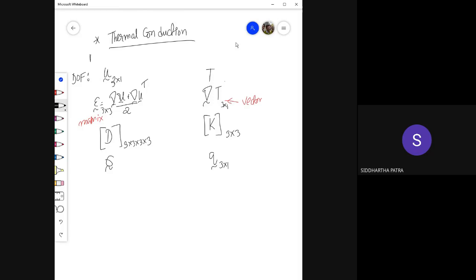There are two quantities. There is Q dot N, which basically gives you the heat flow rate per unit area, because this one is normal to a given surface. So that is how much is going past the surface. Let's say this is the heat flux Q, and Qn is the dot product Q dot N.